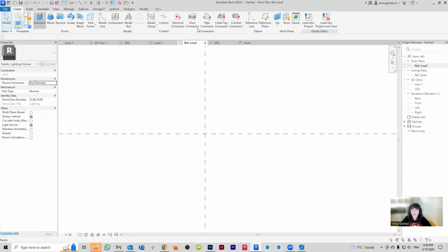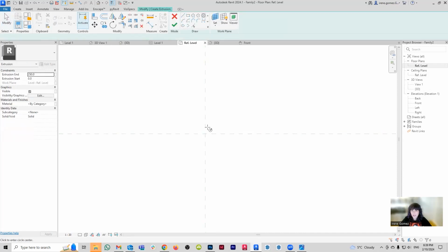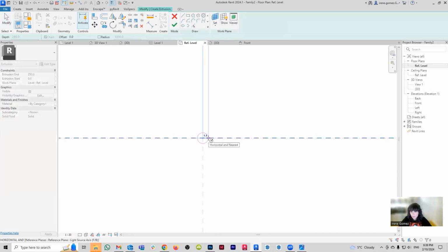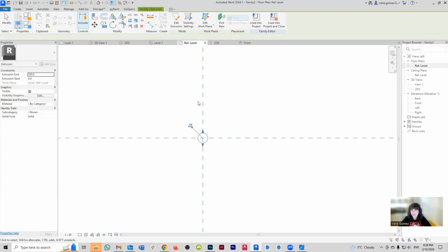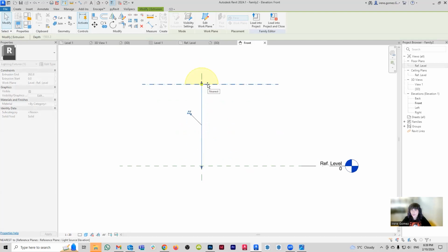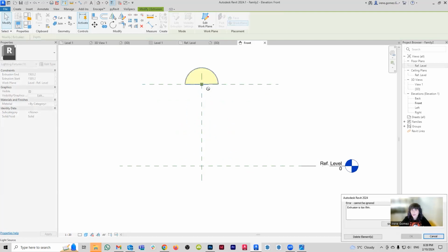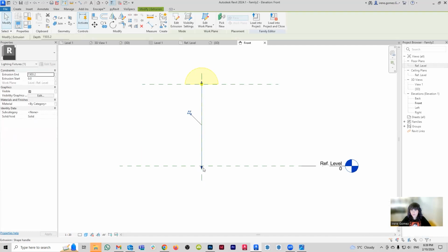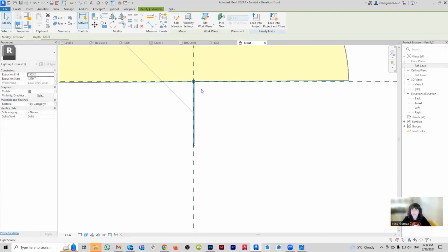So I'm going to go here to extrusion, and I'm just going to make a teeny tiny circle. If we're in millimeters, like 2 millimeters, 1 millimeter, really, really tiny. And then I'm going to say yes. What's going to happen is that when I go to my front view, I just need to stretch this guy so it reaches there. Oh, no, no, that's bad. Bring it close. We're going to need to zoom in.